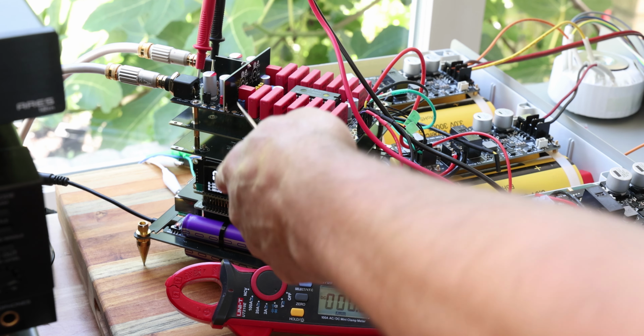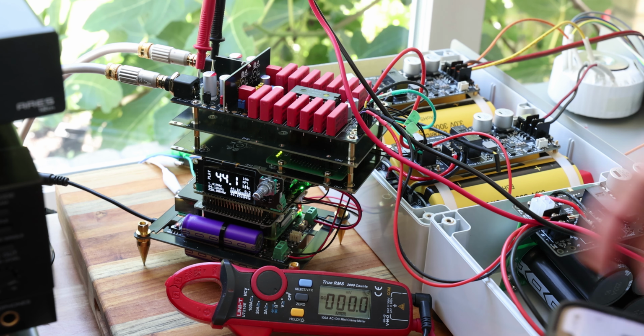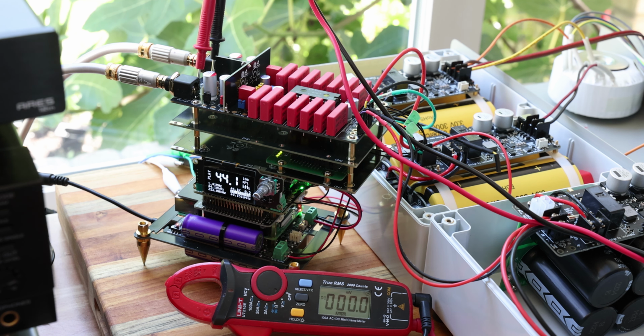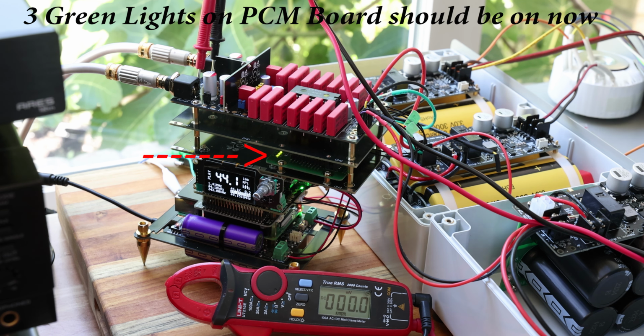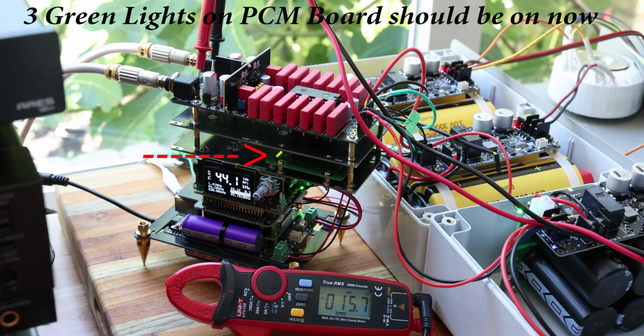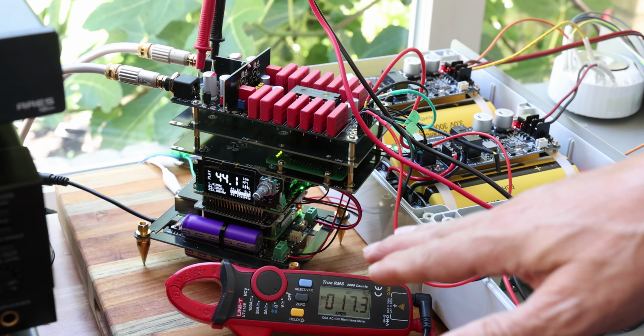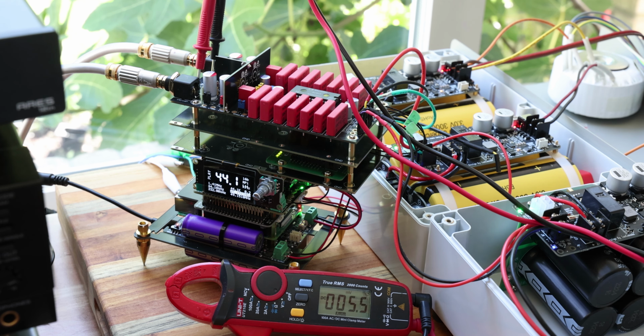I suggest you power your streamer first and just play any song, just play something and make sure it's displaying that there's something going on. And this is when you can actually turn the DAC power on. So I just turned the DAC power on, and you right away see that there's some fluctuation, but that's because the song is playing and it's going up and down a little bit. So now you're going to pause your music, and that should steady up. And this is when you can adjust the voltage.